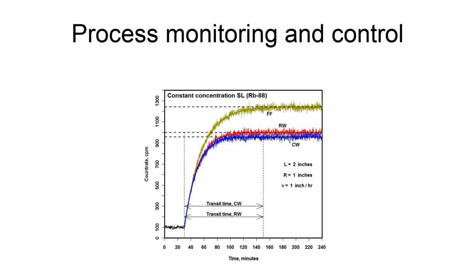Radiation monitors in general have a number of process control applications in nuclear power plants. A major CPAM application in this area is the monitoring of the air intake for the plant control room. In the event of an accident, high levels of airborne radioactivity could be brought into the control room by its HVAC system. The CPAM monitors this air and is intended to detect high concentrations of radioactivity and shut down the HVAC flow when necessary. For use in the USA, Standard 10 CFR 50 Appendix A states: Criterion 19, Control Room.